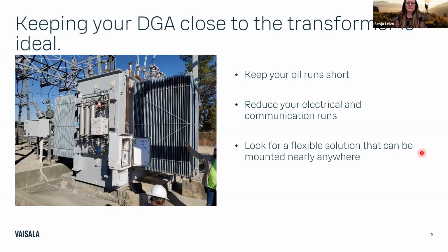If you have a bigger fleet, or you are in contact with other utilities who have similar transformers, a similar kind of operation like transmission, for example, I would start with looking at the 90th percentile of the gas values of my fleet, or the 95th. And again, keeping in mind that the average statistical failure rate is 0.5%.